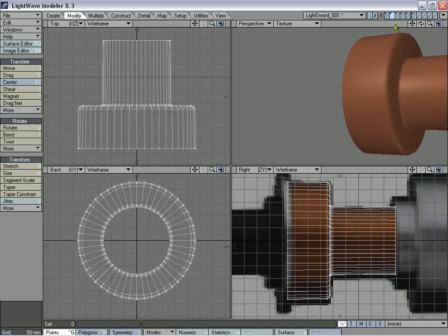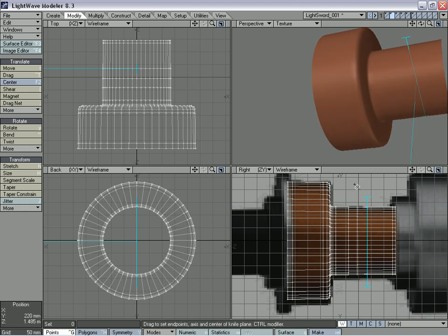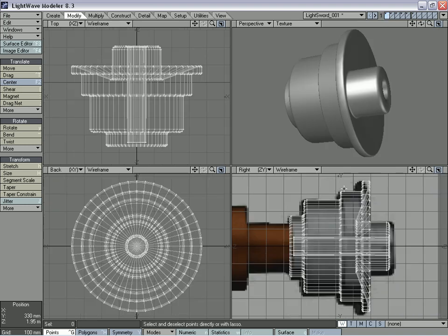And this one will go through and add a few knives to it. And once again, the knife is Shift-K on the keyboard. And I'm also using the middle mouse button again to constrain this knife so that it's perfectly straight, or you can use the Control key. And also, if you have a section like these two that are exactly the same, you could right mouse click along and it'll just create that knife and create a new one. We're going to undo those because we don't need them. And move on to this last section here.